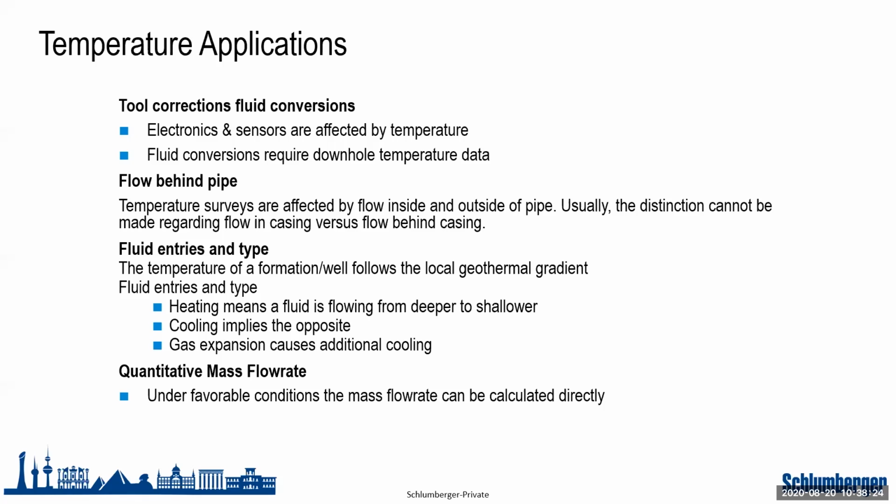Also, it can indicate which kind of fluid entry goes inside the wellbore, as we can see, where gas entering the wellbore is different from water or liquid entering the wellbore. And in some conditions, you could utilize temperature deflection to calculate mass flow rate. But that's not very simple, as it depends on many factors. But it can also be done.